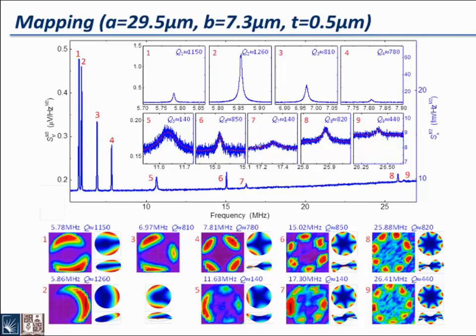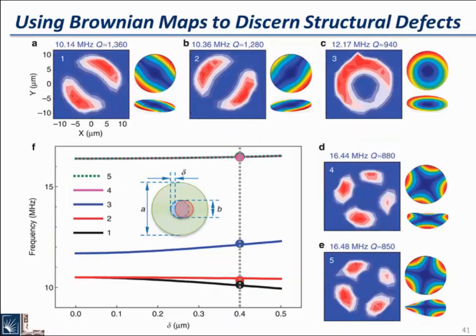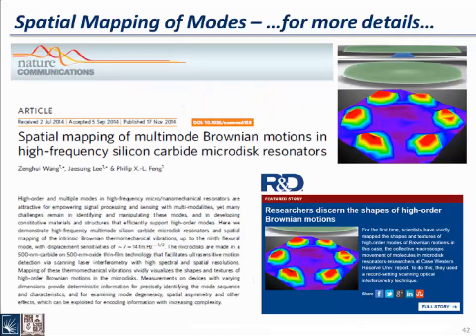We were able to image. The left side of each panel is the experimental data. The right-hand side is simulation. So this images the ninth mode of mechanical resonance, an undriven thermomechanical mode. And with multi-mode as a sensing probe, we can trace back to see how much defects or fabrication imprecision is on a pedestal. So that's the sensing modality using multi-mode.